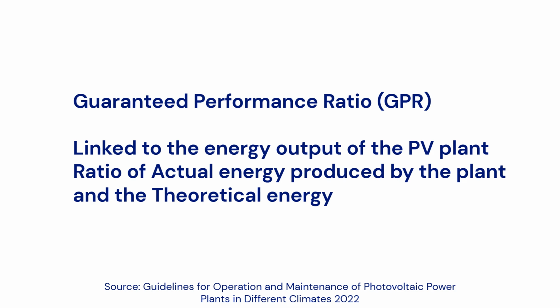This indicator is directly linked to the energy output of the PV plant. It is expressed as a percentage and represents the ratio between the actual energy produced by the plant and the theoretical energy it should produce under ideal conditions. The theoretical performance ratio is calculated during the project contracting phase using typical meteorological year data. Based on this value, the guaranteed performance ratio is then defined in the O&M contract.